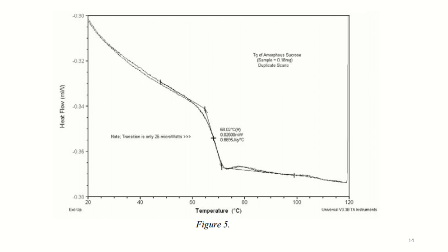For many samples, it is often difficult to detect the glass transition by differential scanning calorimetry even when the sample has a higher amorphous content. This is due to interference from other transitions that occur over the same temperature range.